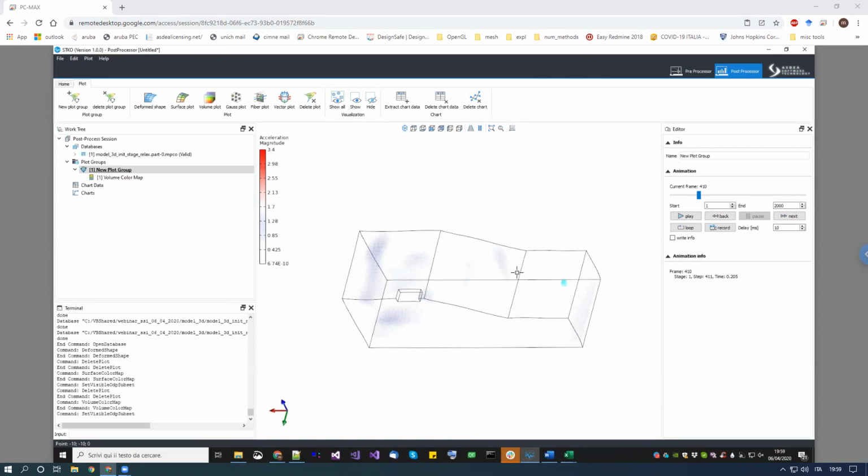Is it possible to use the modified Ibarra-Krawinkler model for the rotational spring with zero length elements? Yeah, of course. The only difference is that when I defined the zero length in this example, I simply said it should be 3D with just 3 degrees of freedom. Now, in this case, you should say 3D with UR, so displacement and rotation, and then you assign the modified Ibarra-Krawinkler-Medina model for the rotational degree of freedom.